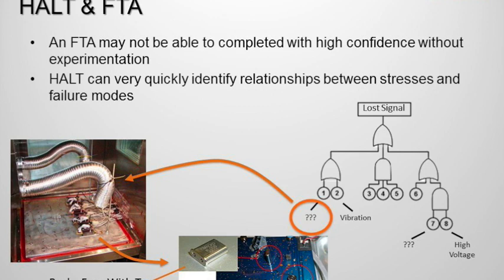And then there's looking at it going in the other direction, with the fault tree analysis helping drive where to look in HALT testing. Let the HALT testing help you with doing a fault tree analysis. So in this case, with the fault tree analysis, coming down to try and figure out what the factors were in this logic diagram, not being able to clearly speculate what would happen in combination with vibration that would lead to the lost signal.